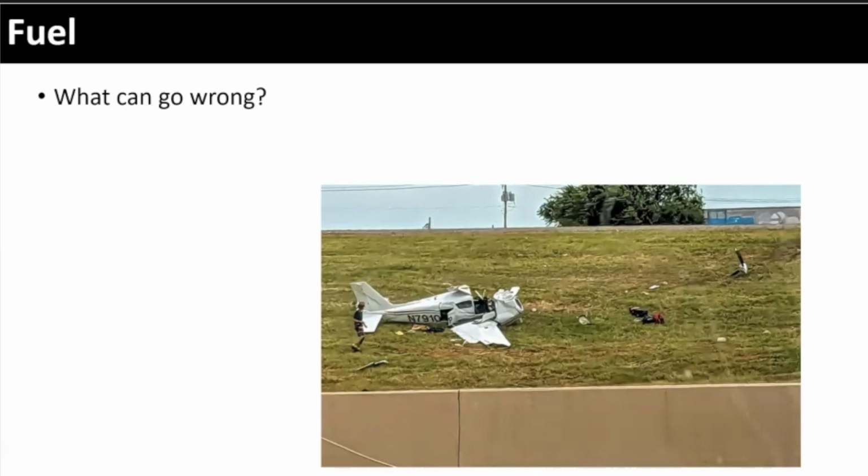Sam failed to do his pre-flight, and the fuel hadn't been tested, and he had contamination coming in from the fuel tank. The airplane was sitting outside. They'd just done a lot of maintenance and overhaul on it, and had just flown it back from Michigan. It sat outside in the weather. They didn't realize that those fuel caps on the top didn't have the right seals, right? Water got into the fuel.